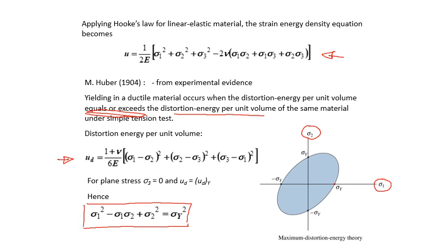principal axis at sigma yield. So we have sigma yield on all four locations on the two axes. If we plot our principal stresses, sigma 1 and sigma 2, and they are both within the blue boundary, then they pass, they do not yield. If one of the principal stresses reaches the boundary or exceeds it, then we say that the component fails due to yielding.